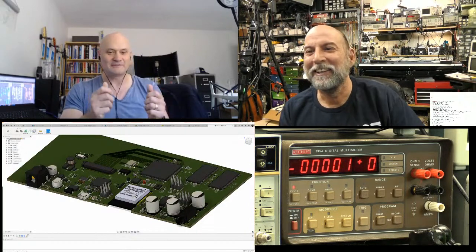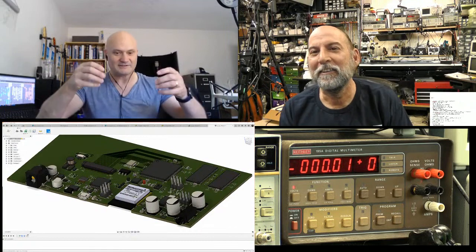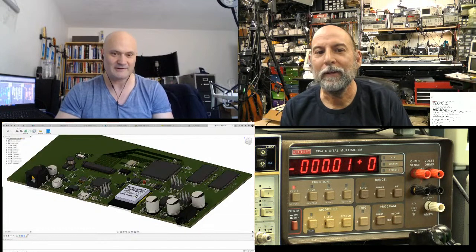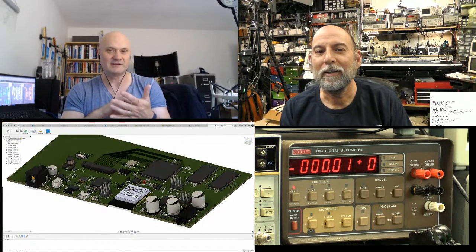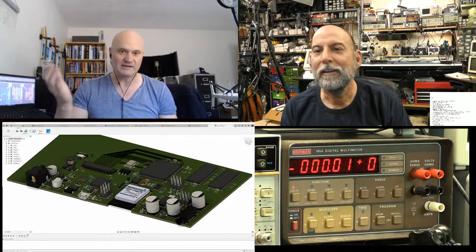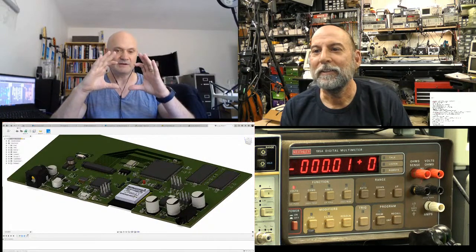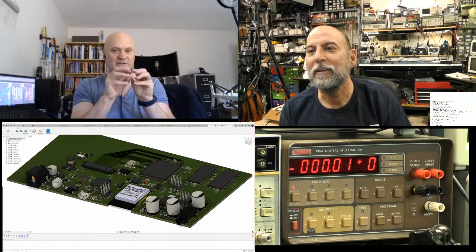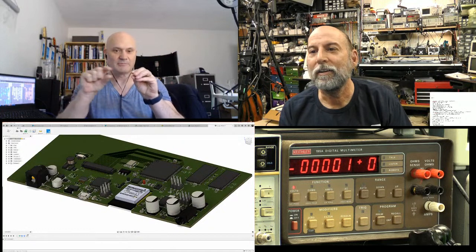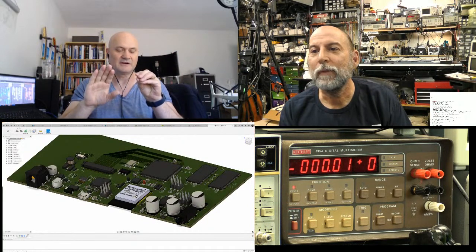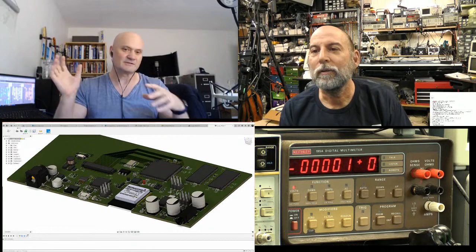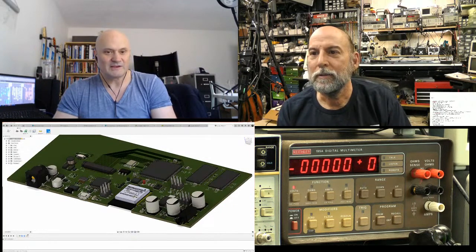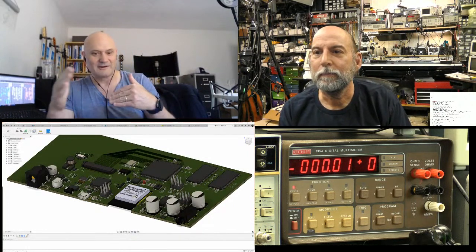Yeah. It's small enough to be handheld, and I could put touch sensors on the side. Maybe I'm still debating whether I do that or not, but because it has a TFT touchscreen on the whole back of the board, it's going to be a nice TFT panel this big with the capacitive touch. All of that goes through the FPGA, and the FPGA as a coprocessor has the ESP32, which also has the audio codec on it because it's got all the stuff built in to just do that.